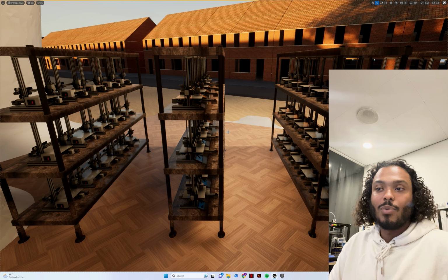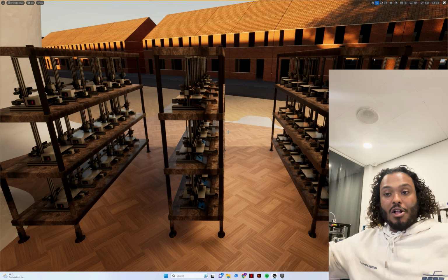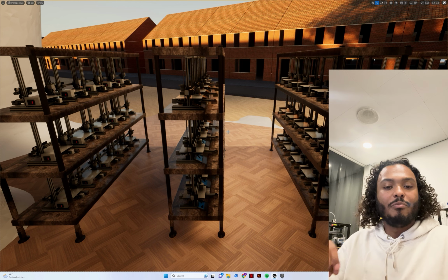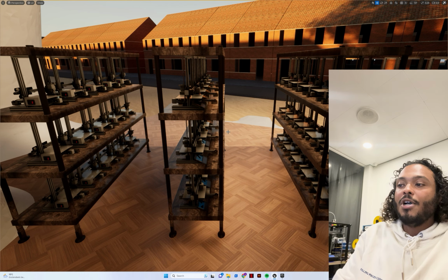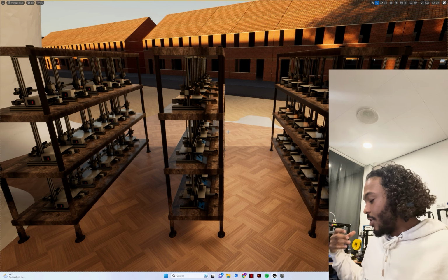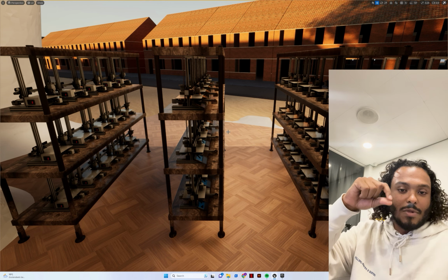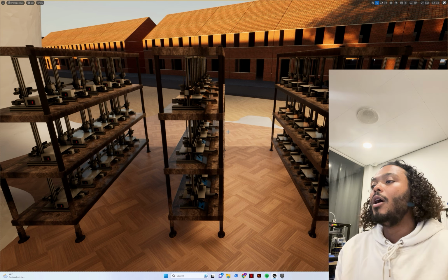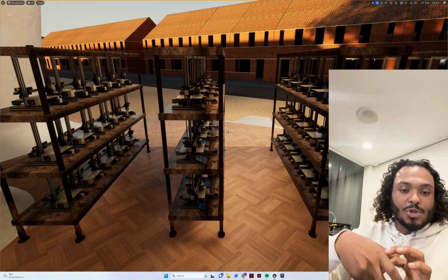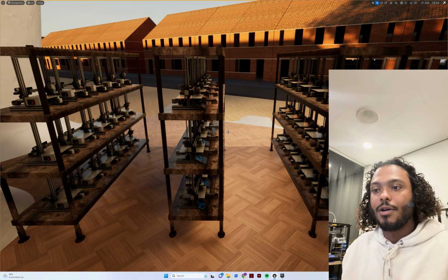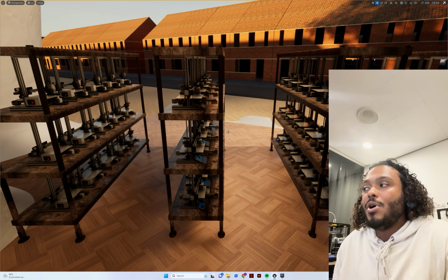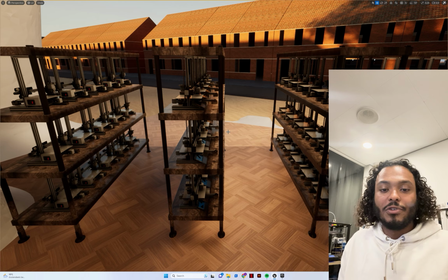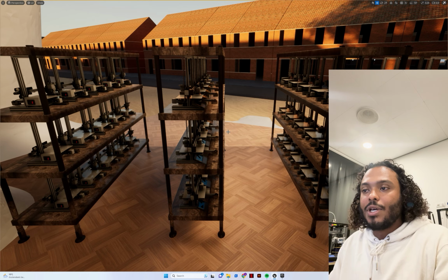And for recycling plastic, I'm also looking into buying bigger, larger-scale 3D printers with a granulate nozzle. That is a nozzle that doesn't use the regular filament with the thin 1.75 millimeter extrusion profile; you can just feed it pellets and it will squeeze them automatically, layer it and 3D print it on a larger scale. So I'm also thinking about getting recycling machines where I can take all of my old filament, put it through a machine and use it again.